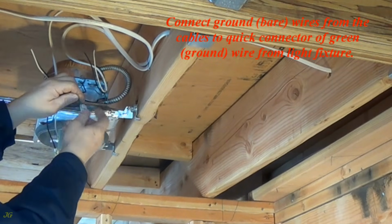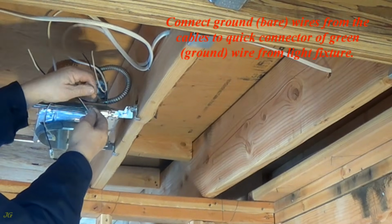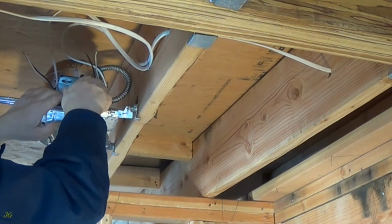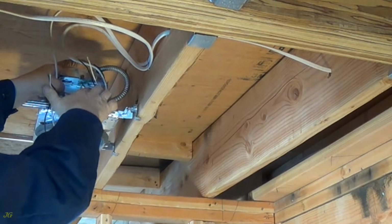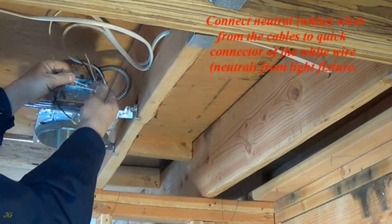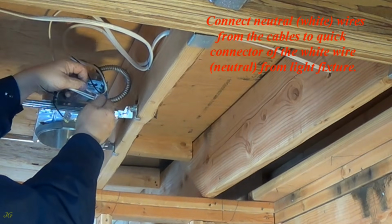Connect ground, bare wires from the cables to quick connector of green, ground wire from light fixture. Connect neutral, white wires from the cables to quick connector of the white wire, neutral, from light fixture.